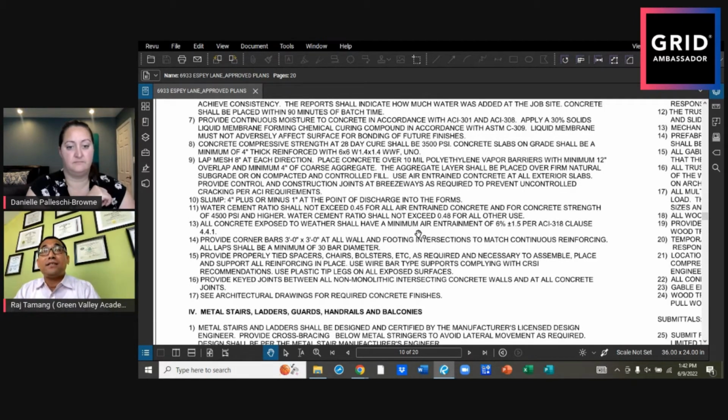And cement is a chemical, so as soon as you pour water, there's a chemical reaction going on, called hydration. That's how you gain the strength. During that process, the water starts evaporating, because when concrete dries, the water should not be there, right? But you mixed the water in. So when the water evaporates, it starts leaving a gap inside. You're not supposed to leave a gap, but now I'm putting that gap in on purpose. And you ask why? Because of what happens, especially in wintertime.